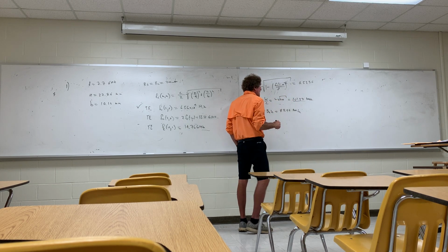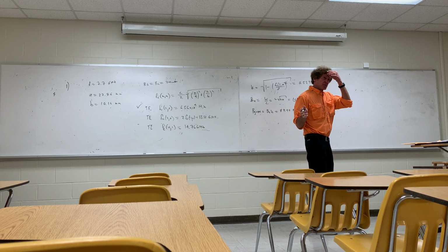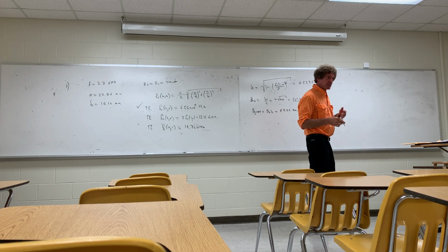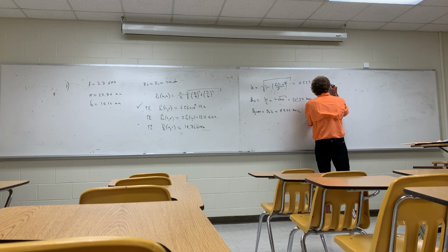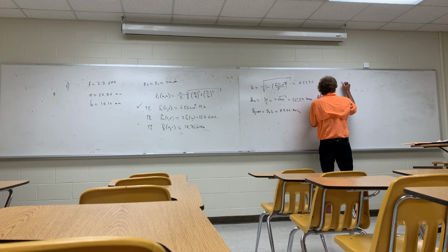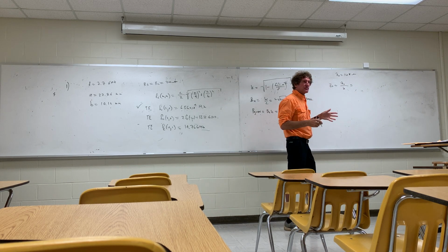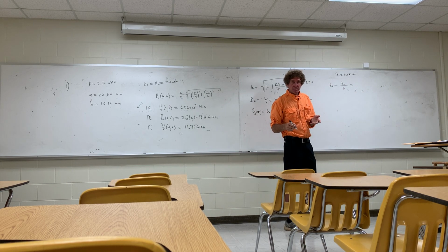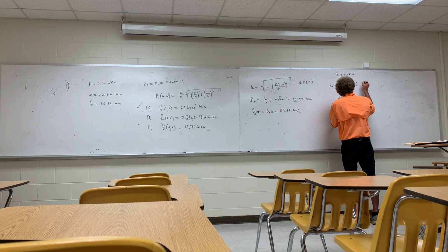All right. After that, we're going to get the impedance of the guide, the characteristic impedance that's going to be used in the waveguide equation. So the next thing is going to be Z naught. And Z naught is really going to be eta naught, where eta naught is simply equal to 377 ohms divided by K. And it's divided by K because it's TE. If it was TM, it would be multiplied by K. Do y'all remember? And so I think that's 740, is it? 720. 720 ohms? Yes, sir.